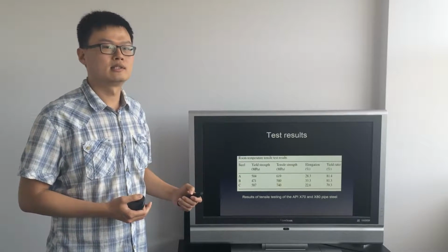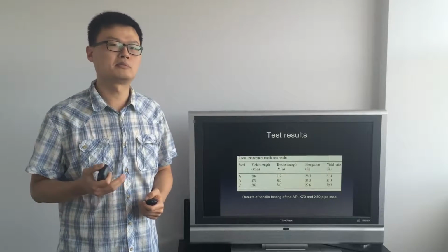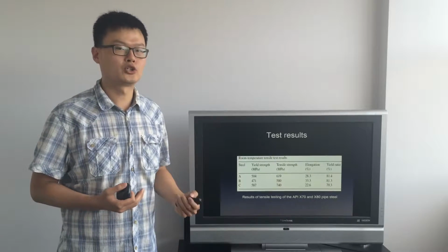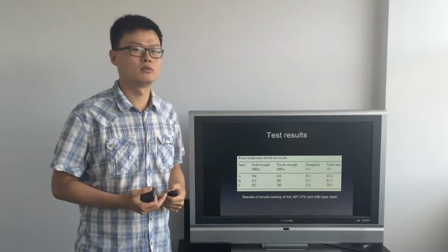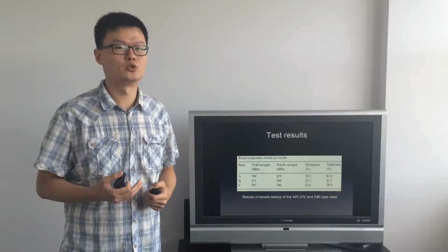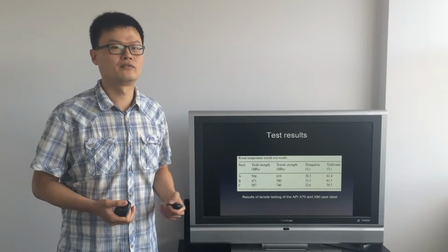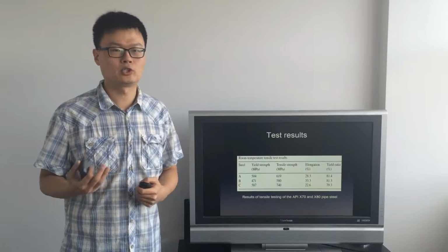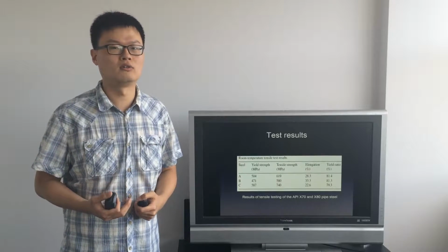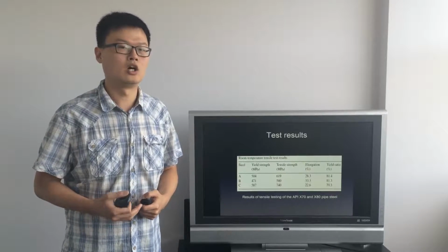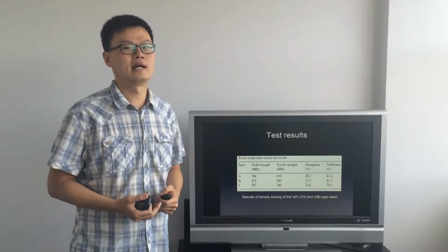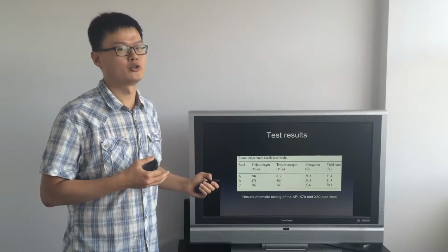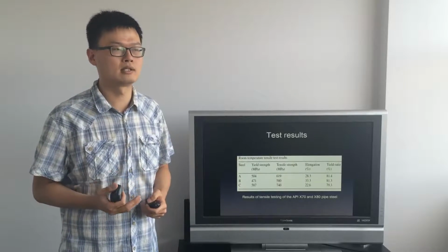The findings illustrate that the two-phase specimens have lower yield and strength than the other one. By contrast, the elongation of the single-phase specimen was lower than the two-phase specimens. As for the single-phase steel, it has higher yield and strength than the two kinds of other specimens. However, that specimen has lower elongation. The interesting point is that the yield ratio of the three kinds of specimens is similar.